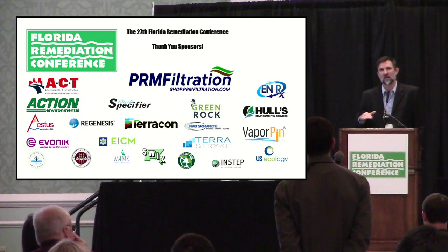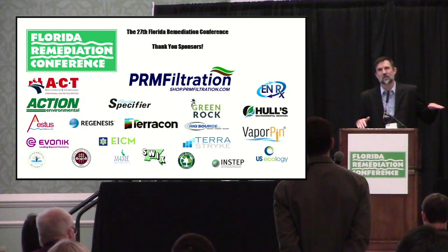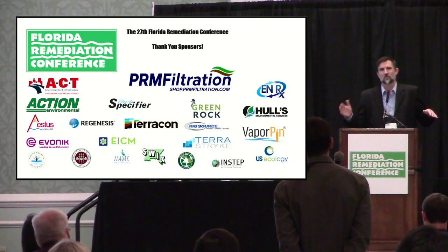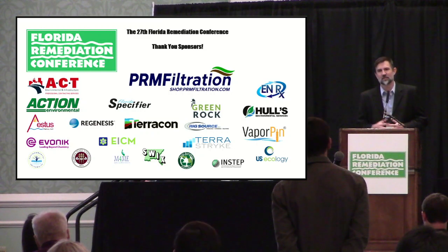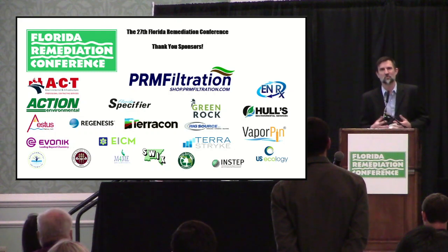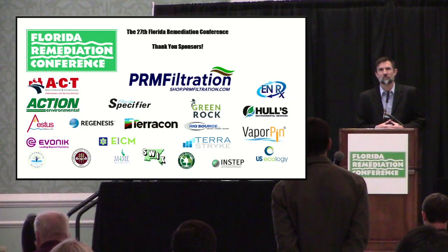That was a comparison of about 20 points with the professional land surveyor using static LiDAR, or a GPS-based survey, compared to what we got with that model output. One of the advantages compared to LiDAR is just the density of points. With LiDAR, depending on the unit, but definitely if it's a plane-based LiDAR data collection, you're going to get a lot more points per square foot with that structure from motion than you will with LiDAR. Great, thanks.